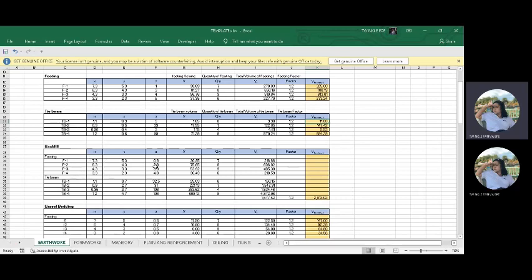We have different sizes of it, different length, different height, and width. To get the volume, we multiply the length, width, and height. And we have the quantity 7. To get the total volume, we multiply the volume and the quantity. And we don't have the factor for our footing. So let's proceed to our tie beam 1, 2, 3, and 4.